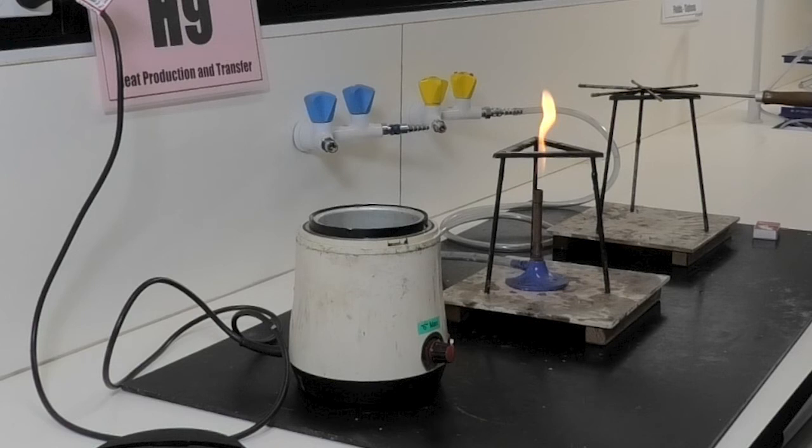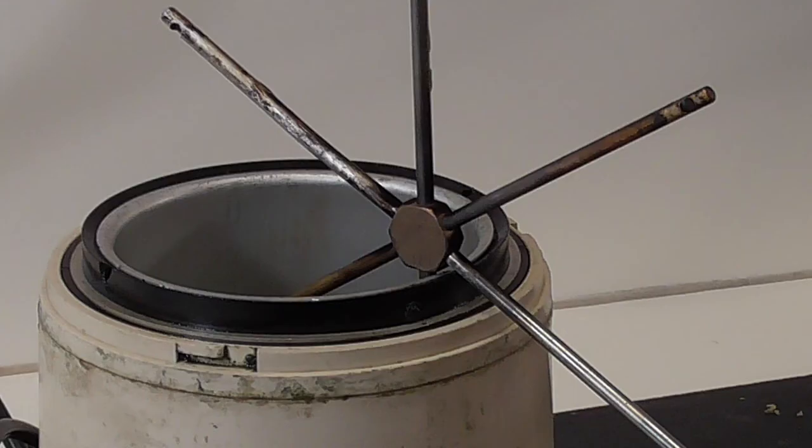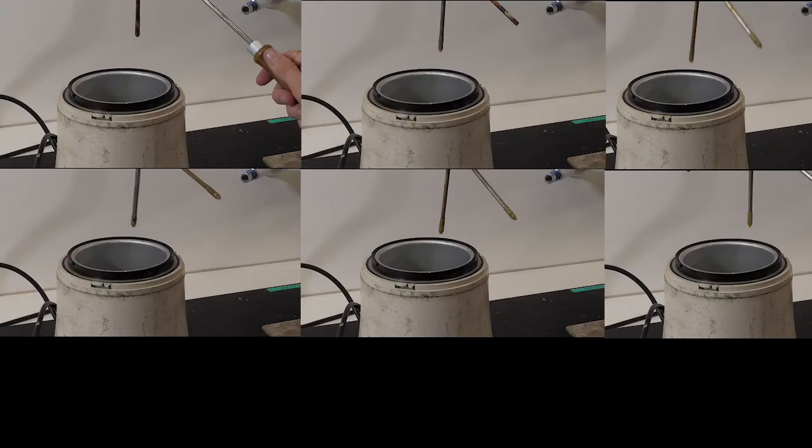The equipment used for Part B consists of a tripod, a heating mat, a heating pad, a Bunsen burner connected to a gas mains by a rubber tubing, our wax melt pot, as well as matches to light our Bunsen burner, and our materials set on a spider. For Part B, we'll want to put wax on the ends of our material. To do so, we rest the material against the edge of the wax pot, dipping in until we can dip in no further, thus getting about 1 centimeter to 2 centimeters coverage of wax on each of the ends of the material, as shown in the photo.